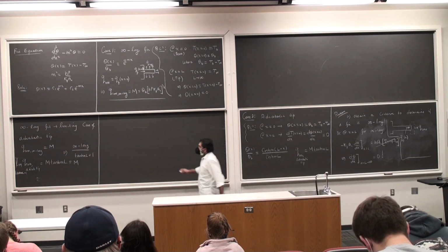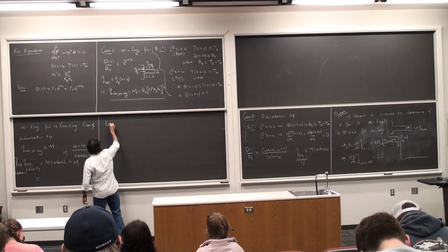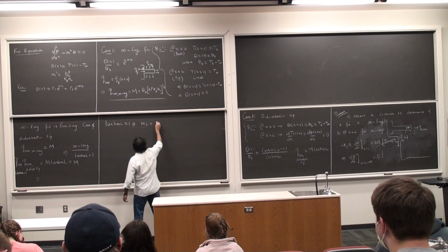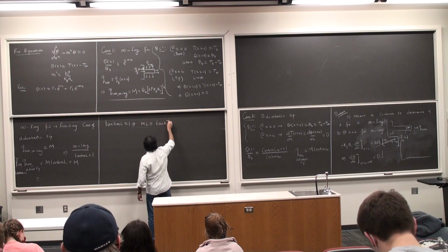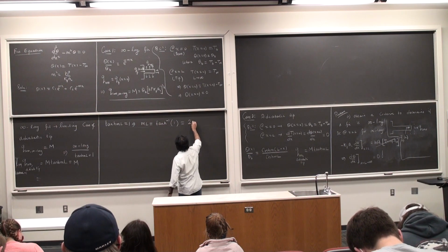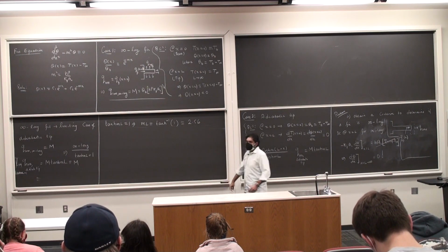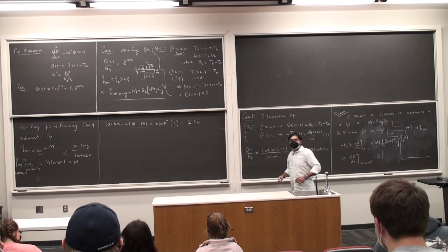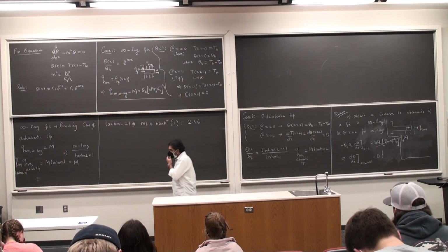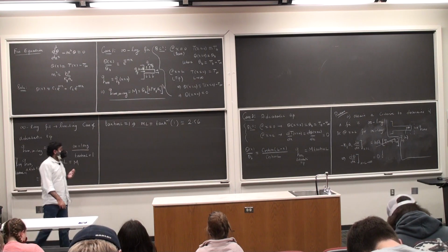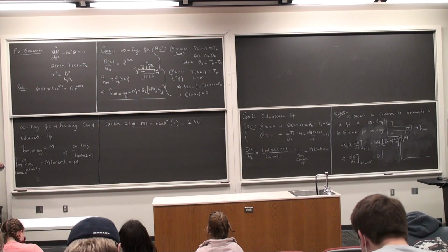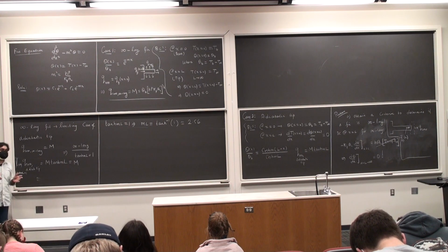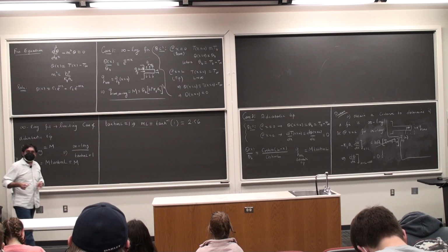Okay, so if I look at tanh mL is equal to 1, if you crank up your calculators, it's e to the power 1 minus e to the power minus 1 divided by e to the power 1 plus e to the power minus 1, okay, exponential. And so we have a criterion for an infinitely long fin. If the product of m times L is greater than 2.56 or 2.6, sometimes people say this is 3, 2.56 close to 3, then you have an infinitely long fin.